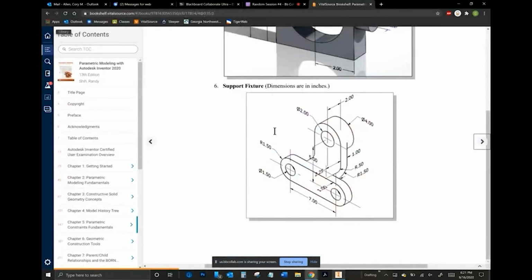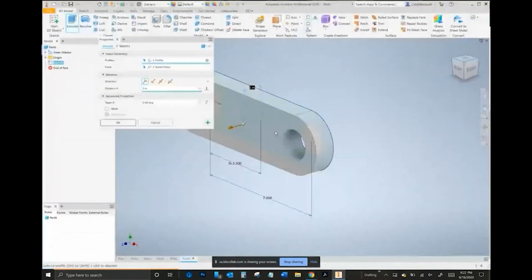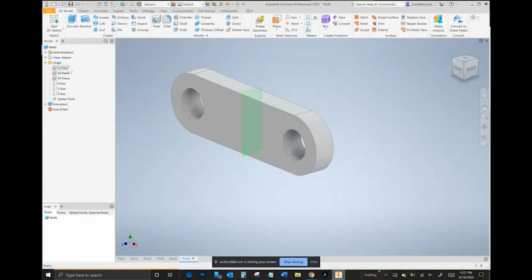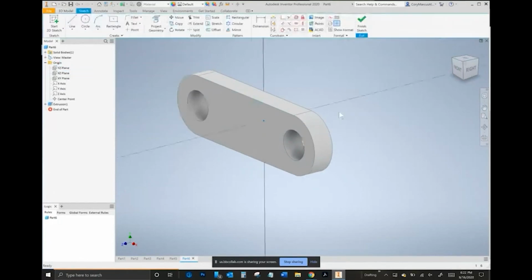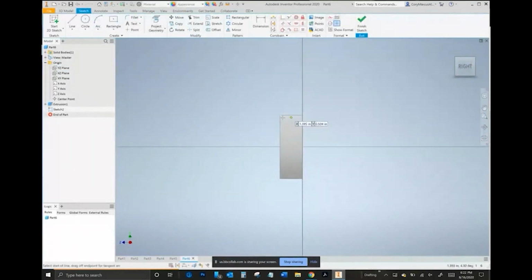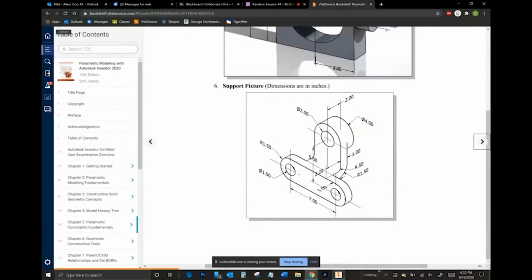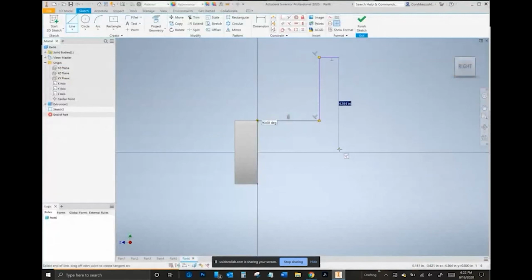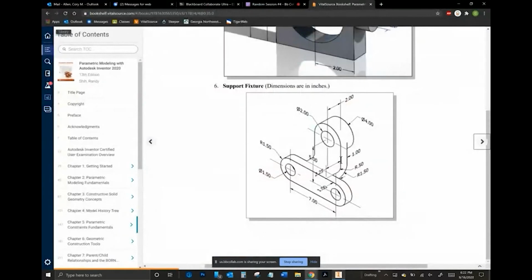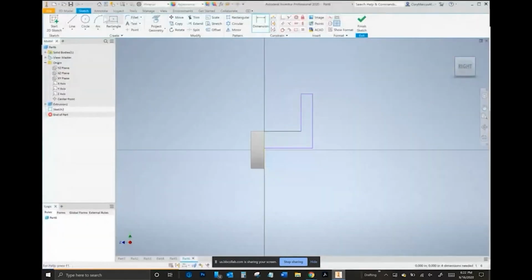It's going to be 1 thick. Extrude away from that sketch, that way we can draw on the plane a little more conveniently. There's different ways to go about this. I'm just going to draw the rectangle and then I'll add the rest. There's not like a great way to draw this little profile. It's going to be 1 thick throughout, it looks like.